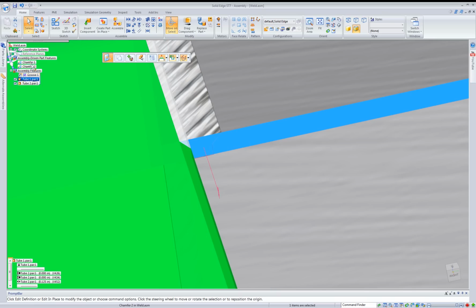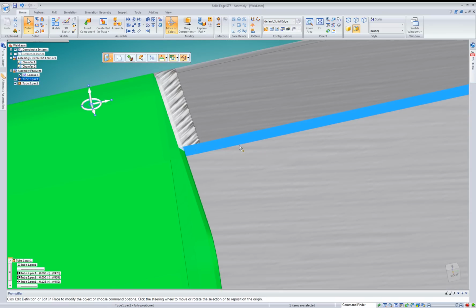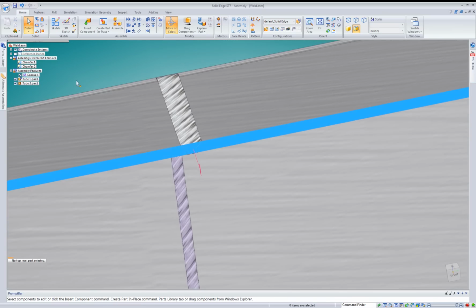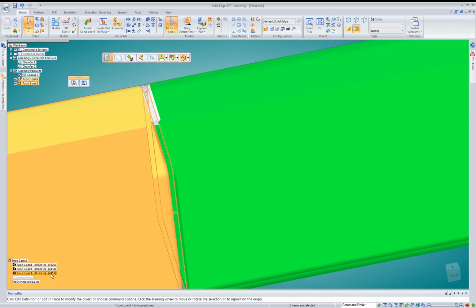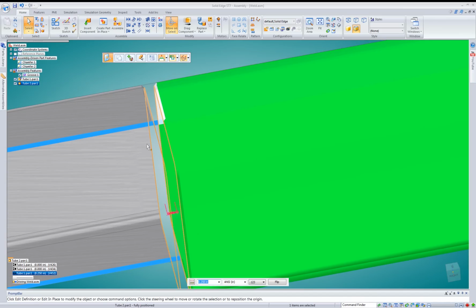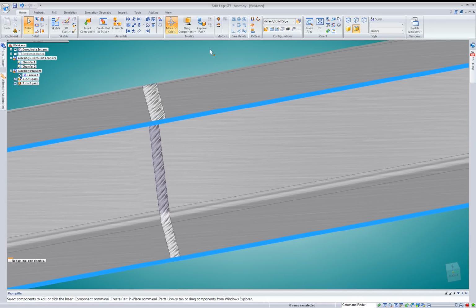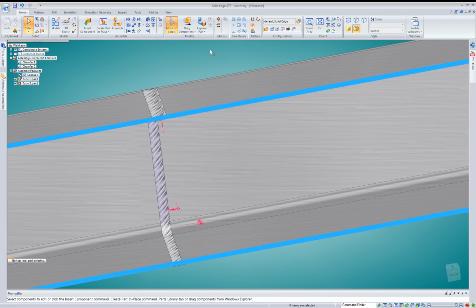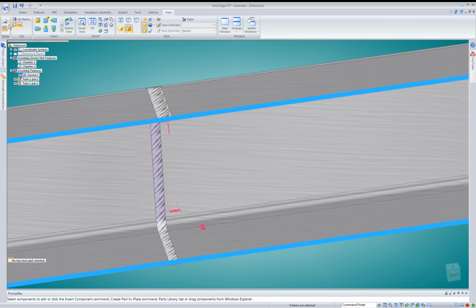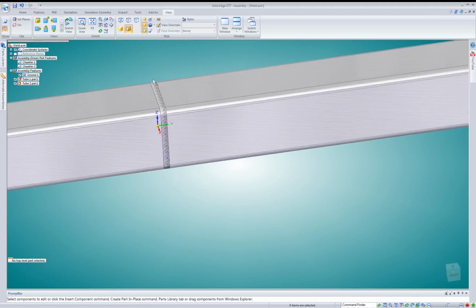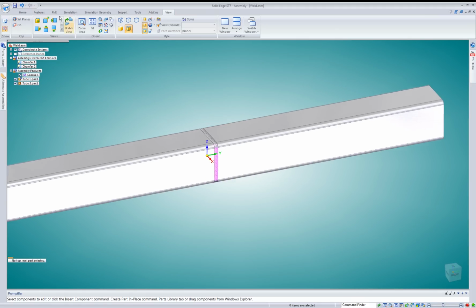So there's the assembly feature, and of course the two assembly driven part features. They can be used in conjunction. The chamfer is at the part level, but the actual weld bead is in the assembly. Any time I adjust the spread distance, which I have set at 1/8, this is more than you would ever do with a 1/4 inch, but just to show that the weld automatically adapts and moves with it. There we have it. Okay, let me turn that off.